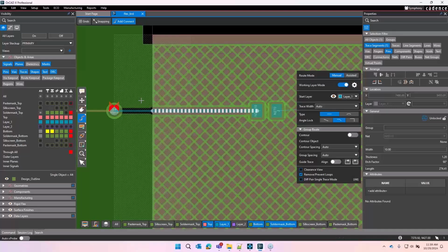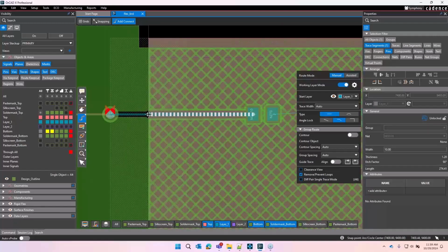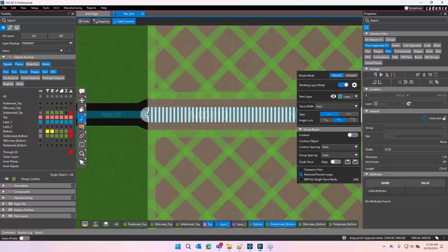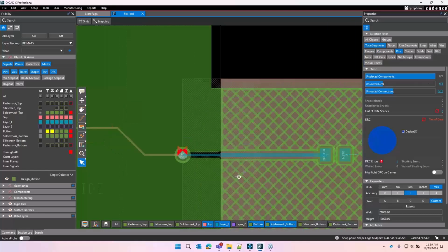First off, as we transition to this flexible region, you can have your trace width change. So Lauren was talking about the trace and space. So this is your trace width. You can see that that has gone from something small to something larger. And you can have your spacing change as well. I only have a single net, so you can't see that. But you can have that change automatically. The way you do that is with region rules. So let me show you those region rules associated with that shape right here that we have.